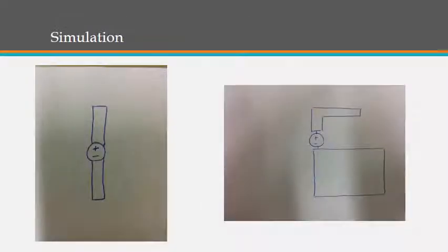We'll be covering an inverted F antenna, which is simply a dipole antenna, as you see on your left hand side, where the bottom half is just expanded out and the top is just bent into an L shape. It is called an inverted F antenna because it looks like an inverted F. With this antenna there is a capacitive impedance, which can be canceled by putting in a parallel inductance to match it up. The specialty about this antenna is that it supports both radiation and impedance matching. A typical F antenna is used in the iPhone 4S and also several other devices.